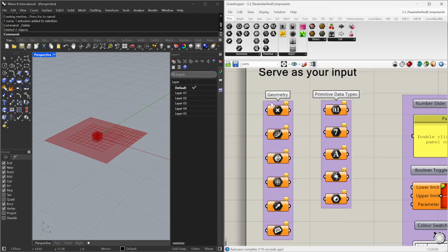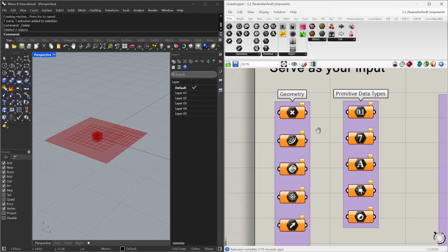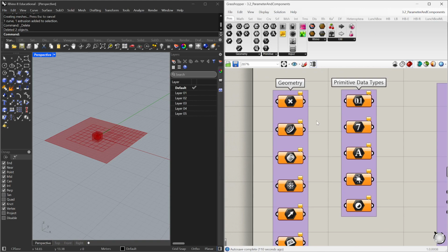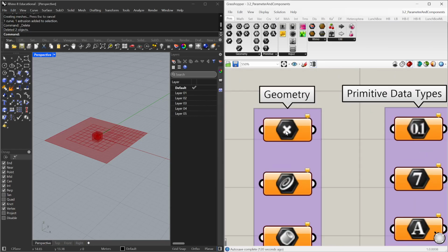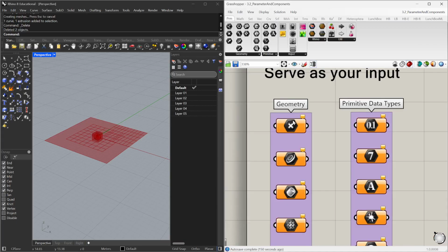Just a quick note. When I'm dealing with parameters, this is something that is collecting data. So it's something that is holding data. Let me tell you what I mean by that. Anything that has a hexagon on it is a parameter that is holding data. In this instance, if I hover over it, this tells me this is point information, so I can only put points inside of this. The next one, for example, is curve information, so it can only hold curves. I can't put points inside a curve parameter because it's for curves, and so on and so forth.